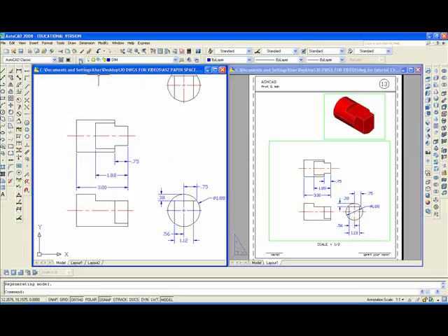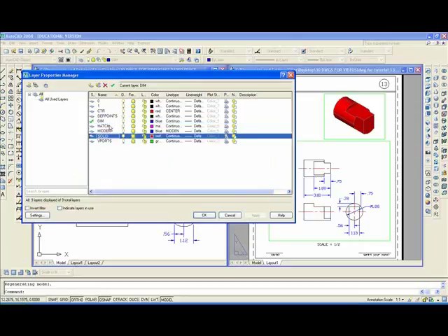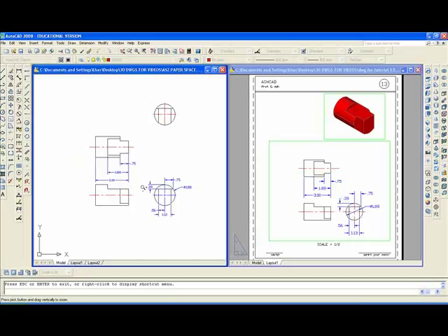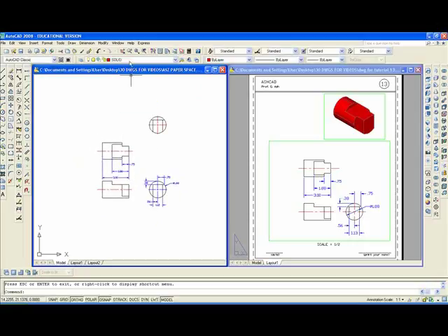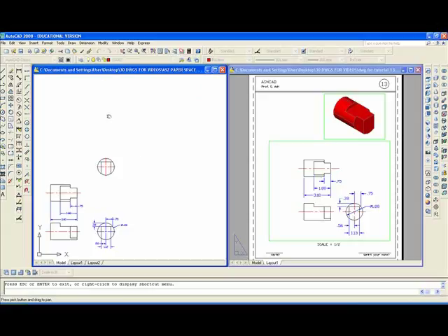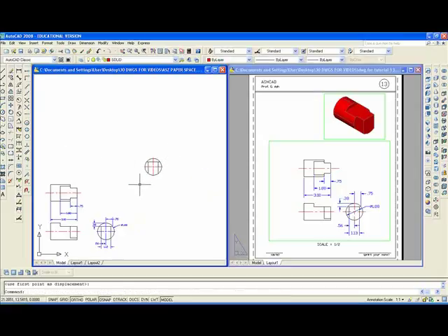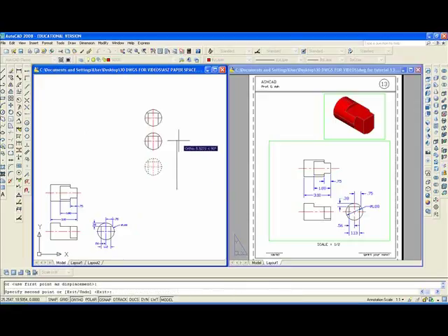Now we'll want to try and make a solid model of the object, so we're going to make solid layer current. Okay. I'm going to pan, zoom real time, make it smaller, then pan over, exit, pan, and I'm going to move enter the solid thing, put it over here, say like that. Also, I think I'm going to have to copy it. So I'm going to type CO enter or copy. I'll copy it 3 times. I'm not quite sure why yet. Let's zoom in on a couple of them.